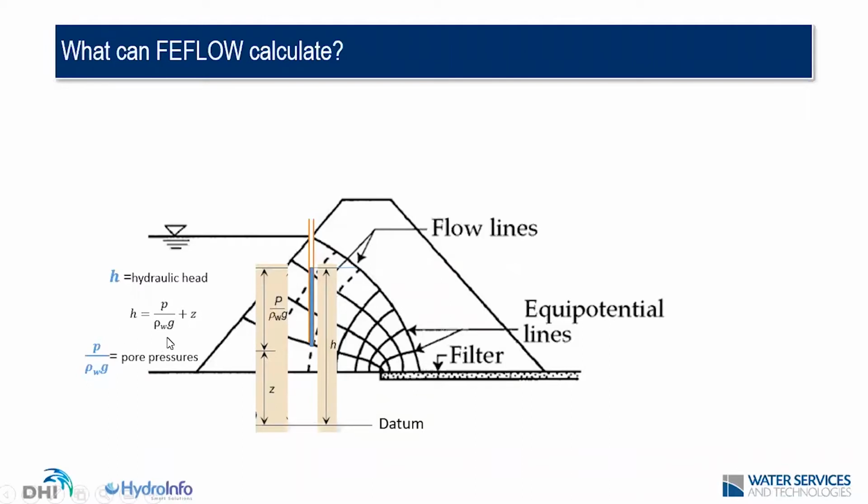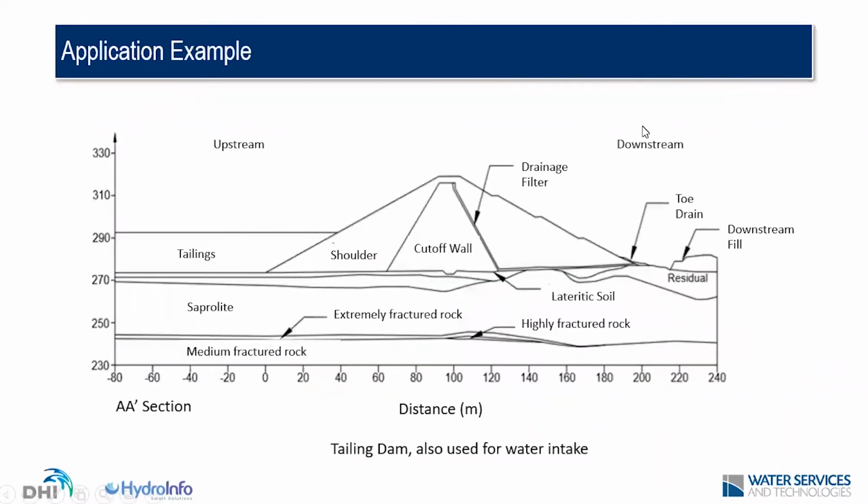Pore pressure is one important parameter. FEFLOW also calculates flow rates, so you can know how much water to expect to collect in the filter, which you can use to design the dimensions of your filter, for example. So without further delay, let's view in practice an application example using FEFLOW of this dam.